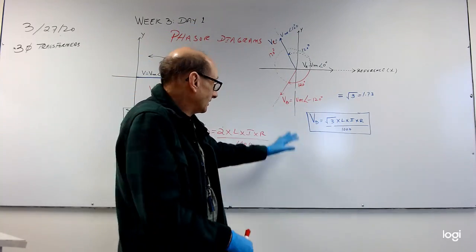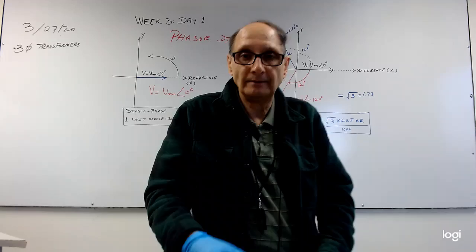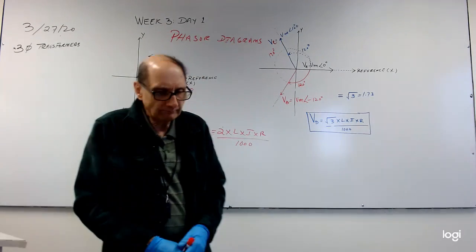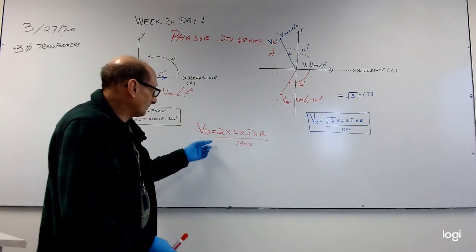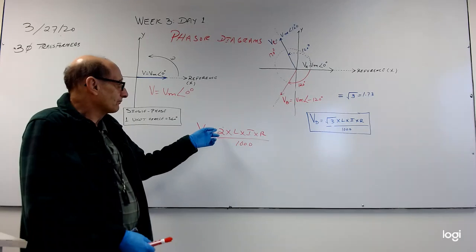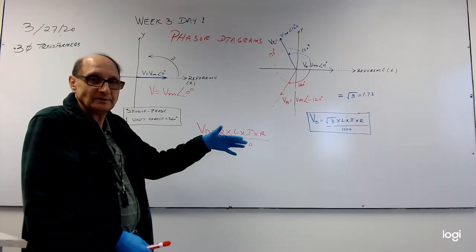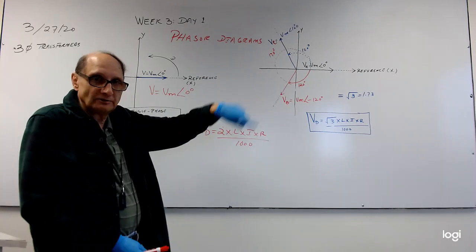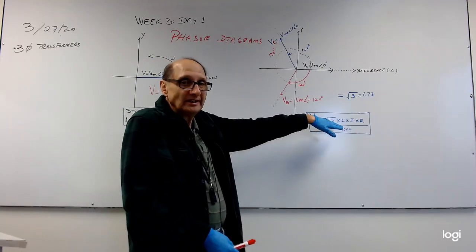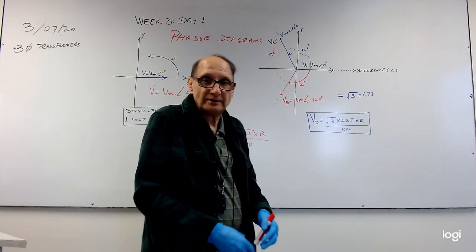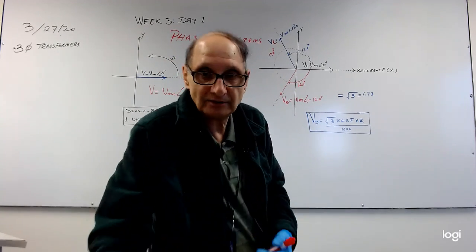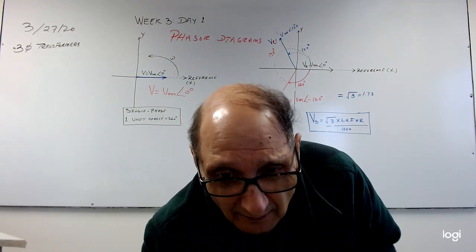So there are 360 degrees in one cycle. Okay, so hopefully you understood that part. Just remember, when you are doing the voltage drop and you look at the voltage drop 2 times, 2 conductors, 2 wires, round trip, square root 3, not 3, because of the angular difference. Okay, so I'm going to pause and start off with another topic.